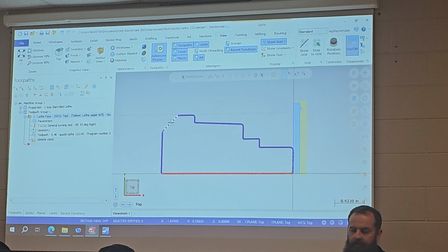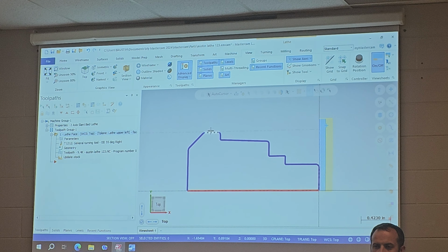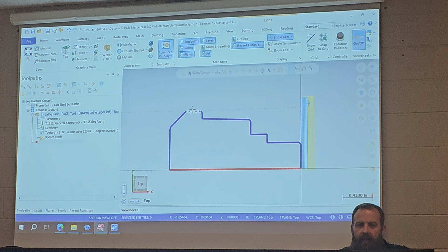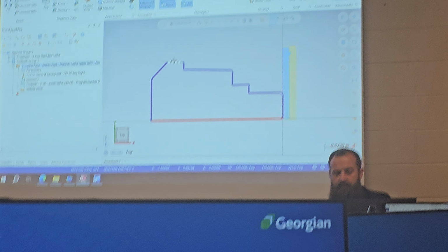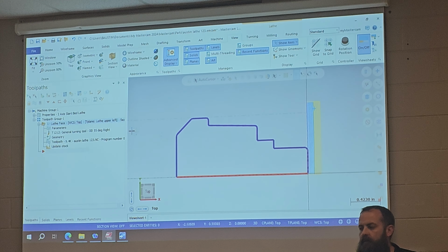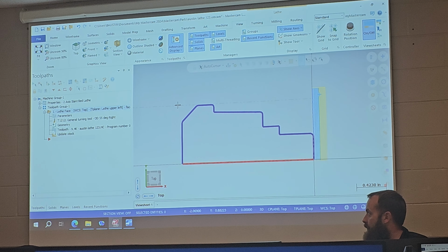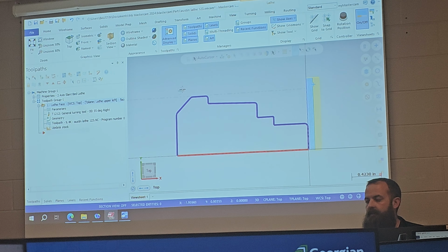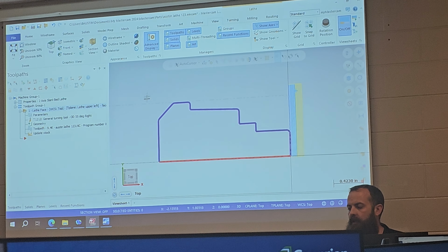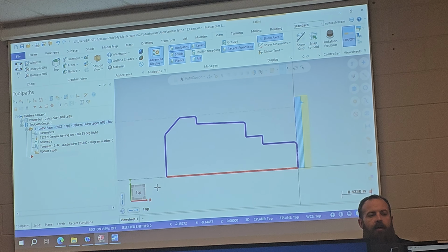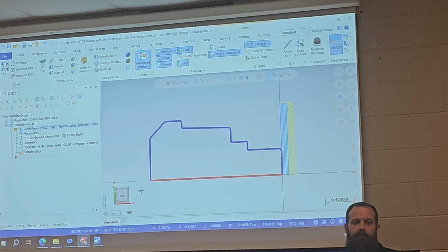When we use line geometry to control the tool path, it's both controlling diameter and length. We're going to make some modifications for this line geometry to provide the result we want. When we actually go and part this thing off, we're going to want to do the chamfer plus part it off in the same operation with the parting tool.